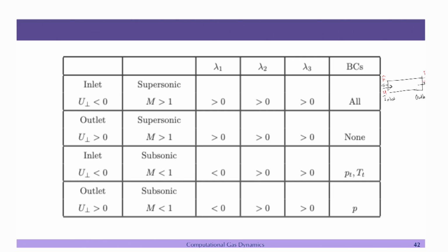If you take the vector u, then u dot n less than 0 means it is inflow, since u is in this direction and n is in this direction, so the product is negative. On the right hand side, the normal is in this direction and the flow is also going out in this direction. This is my n and this is my u, so u dot n greater than 0 means outflow. The flow is going out. This is the general definition.